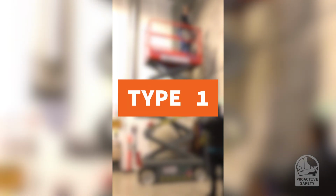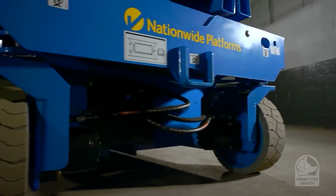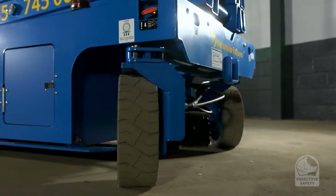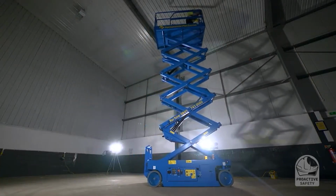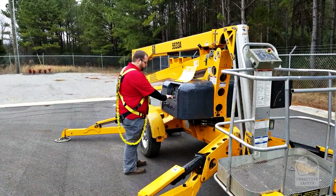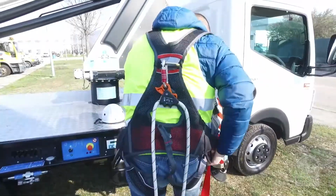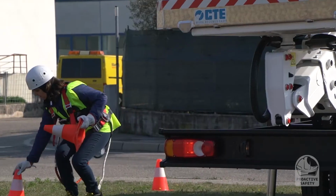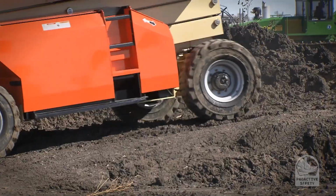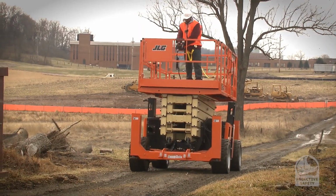Type 1 are lifts and aerial platforms designed for use on firm, level surfaces. They are ideal for indoor work and in areas with uniform terrain. These machines have a limited ability to level on uneven terrain. Type 2. Type 2 equipment is suitable for use on less firm and level terrain. They can adapt better to uneven surfaces and moderate slopes. They are versatile and are used in a variety of environments.